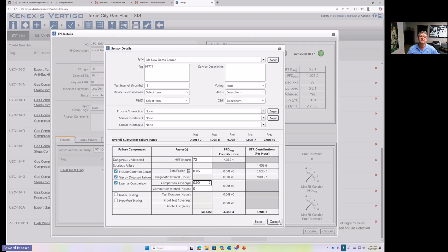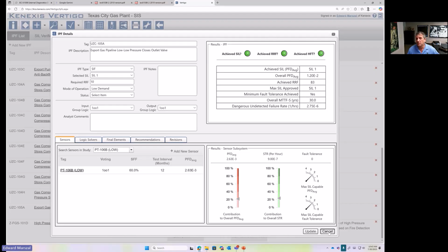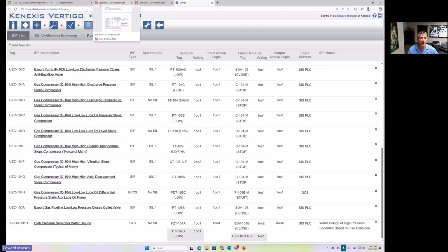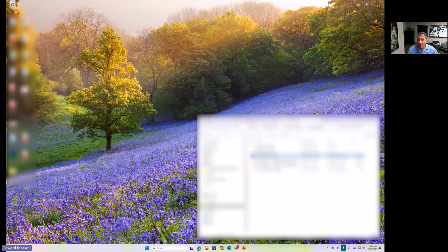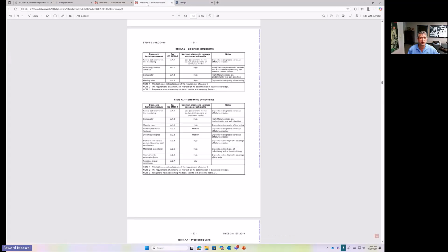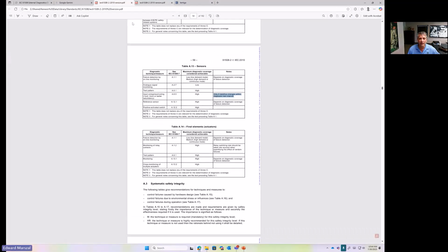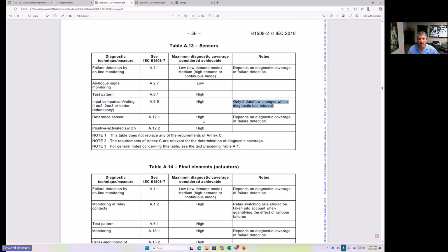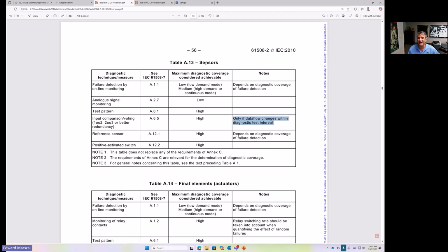So when we're talking about equipment vendor in the weeds details, we need to drop 61511 and go back to the mothership, go back to the umbrella standard IEC 61508. So let's go ahead and take a look at what IEC 61508 says. Okay, so I'll make a long story short, and I'll explain where all this stuff comes from in just a second. But IEC 61508 says in table A18 on page 56 of part 2, there's a table that